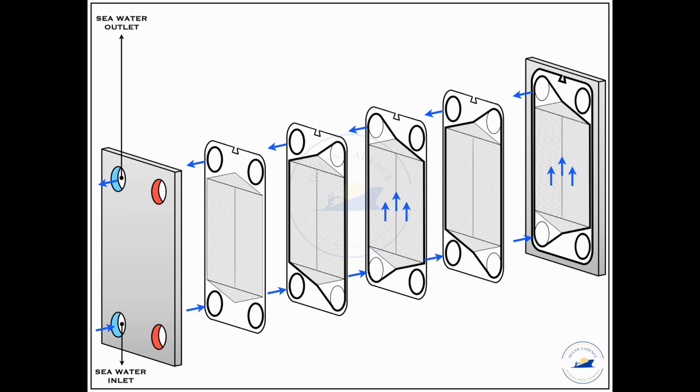The first plate, which is often called the cushion or the spring plate, is used to tighten as well as provide a sealing surface on the main tightening plate or the shell plate. This first plate is the one which has no flow of fluid medium between itself and the tightening plate, because on the other side of the tightening plate there is no heating or cooling medium, and the thickness of the plate is different, so there is no flow between this and the first plate.